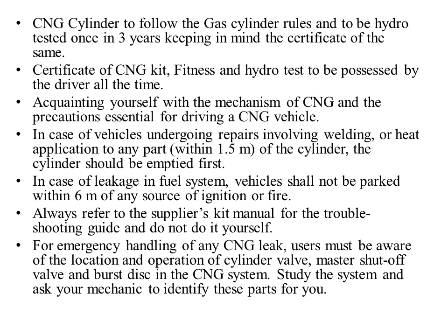And if there is any emergency where we have to handle a CNG leak, the users must be aware of the location and operation of the cylinder valve, the master shutoff valve, and where the burst disc is in the CNG system. So to familiarize ourselves with the location of these, we should study the system and ask the mechanic to identify these parts for us.